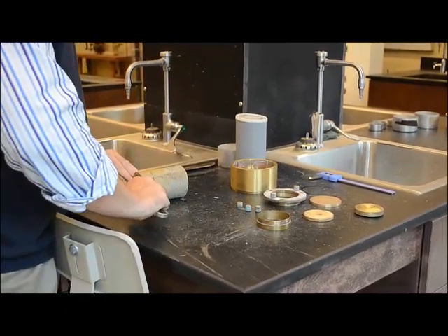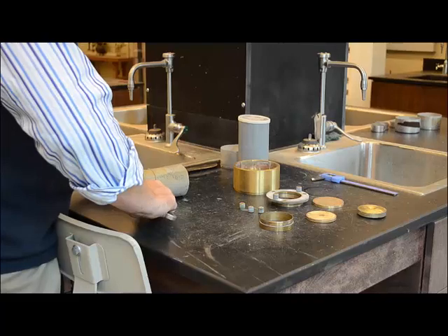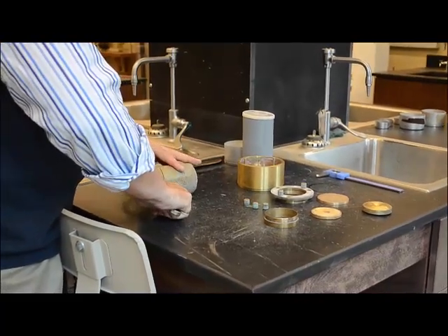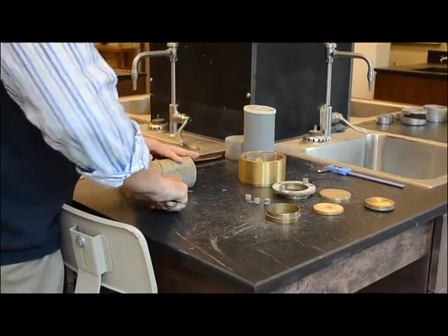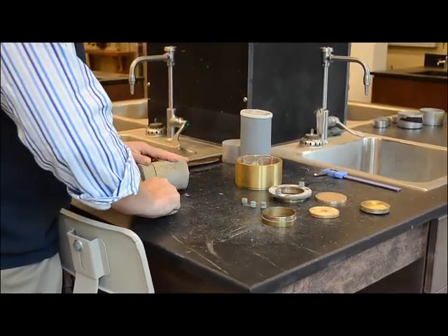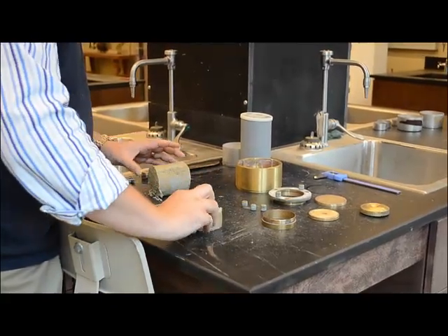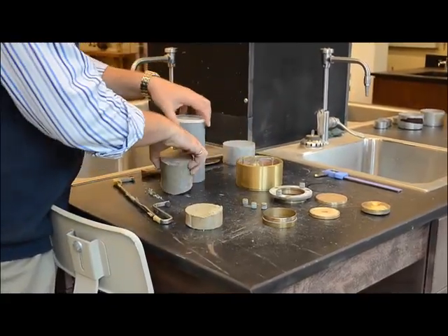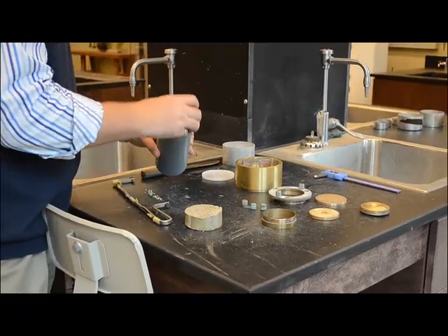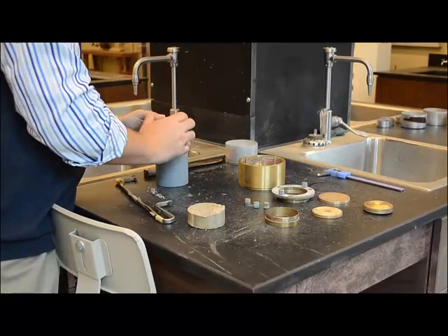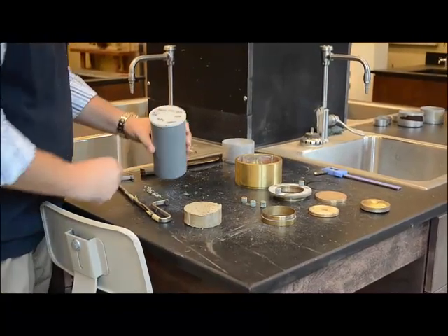And this is an undisturbed sample from a Shelby tube, and we're going to try to minimally disturb it as much as possible. Be very minimal with the amount of disturbance of that sample itself. And so we want to restore the rest of that sample too, and hopefully when you're in the laboratory you can get another portion of that sample.